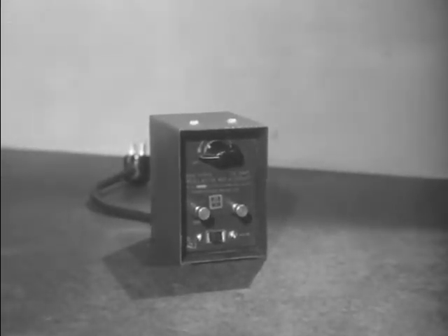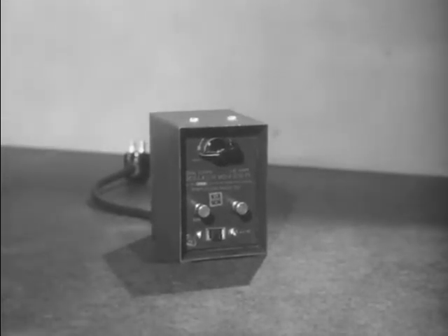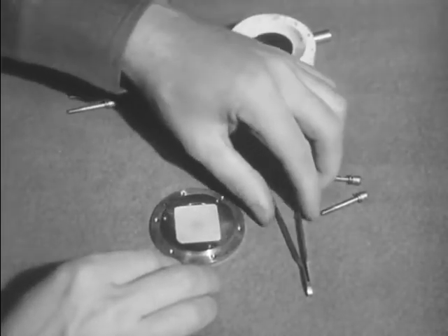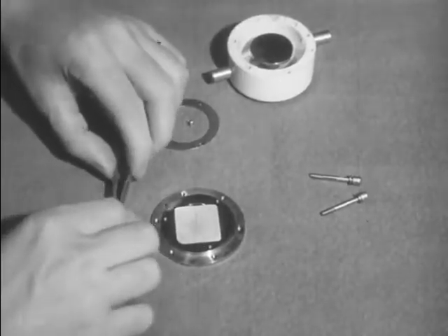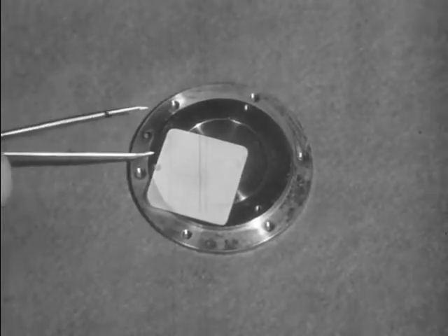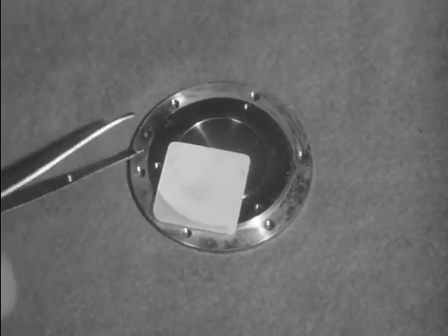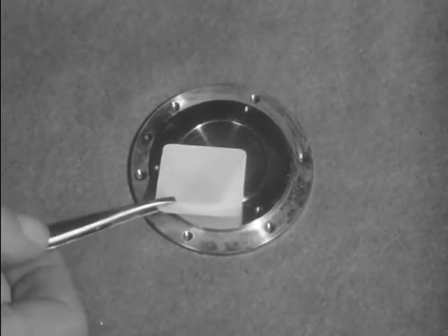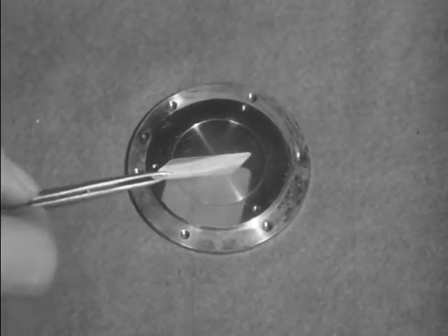Another oscillator is the crystal-controlled type, designed to operate on one or more specific frequencies and is not variable. The important thing in the crystal-controlled oscillator is quartz. Quartz, when cut and ground to accurate dimensions and placed in an electrical field, will vibrate at a particular frequency determined by its physical dimensions.